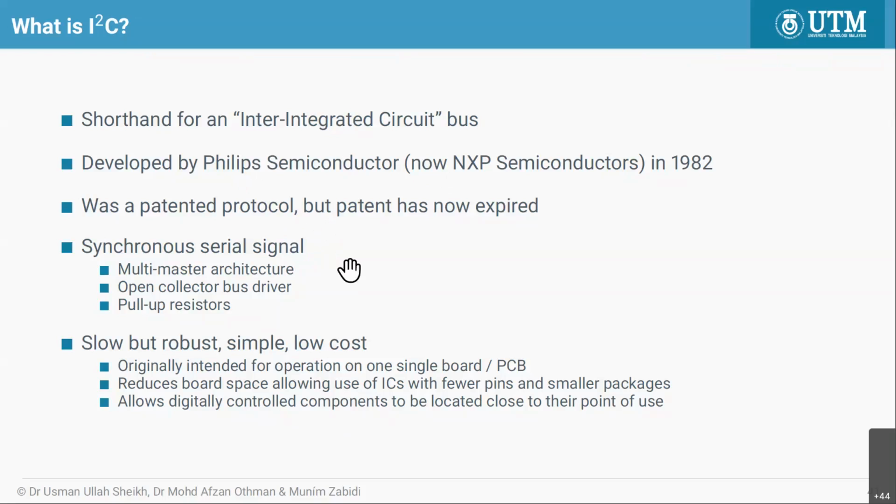And it's a multi-master architecture, which makes it different from some other kinds like USB. For example, USB has only one master and multiple slaves. I2C is multi-master, and it uses an open collector bus driver.